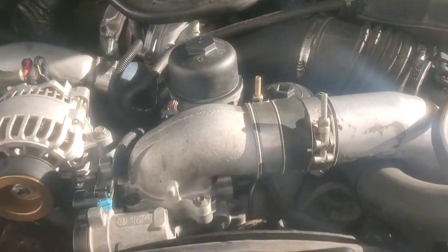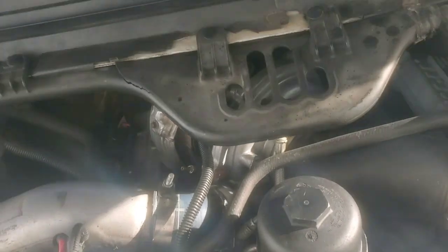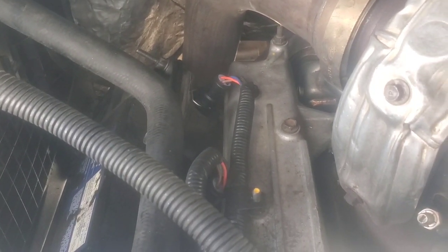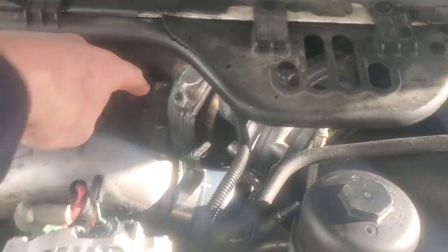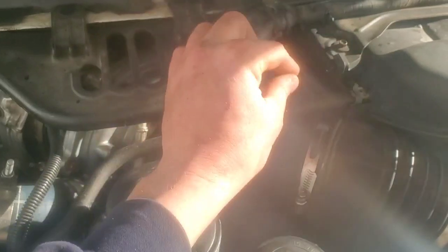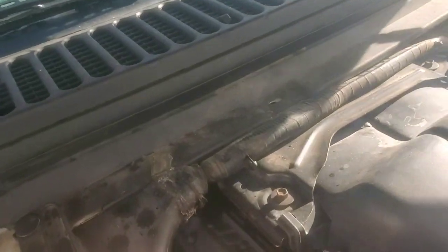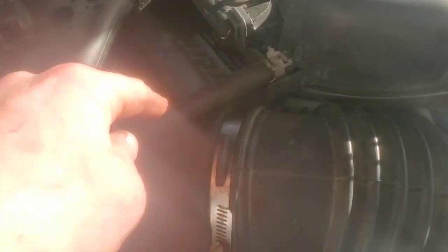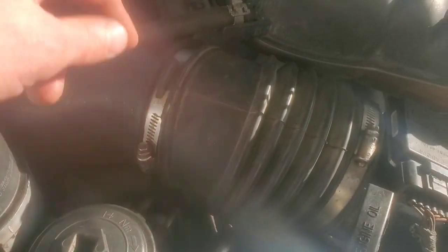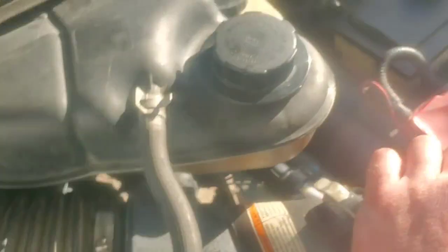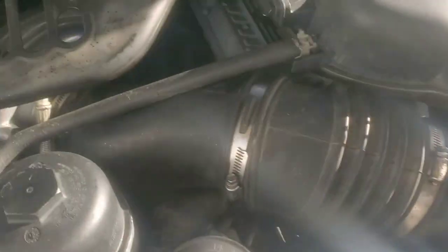The way these wiring harnesses are, you can see we've got a new wiring harness in here for all the injectors. That harness pretty much loops around here, and it's got the two back plugs in the FICM, and then the first plug in the FICM comes into about this area right here. The other plug, or the main wiring harness, loops around through there and goes over to this PCM, while everything else branches off.